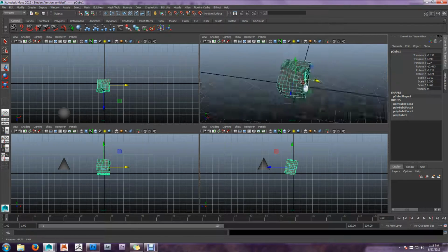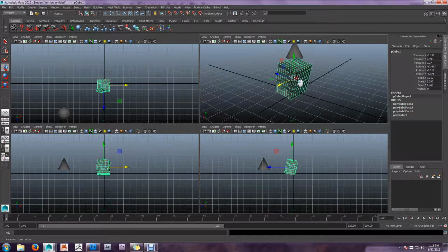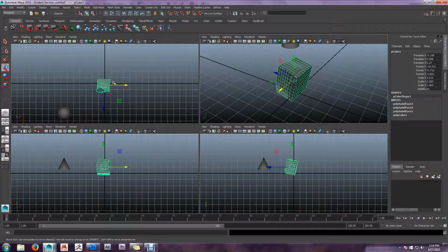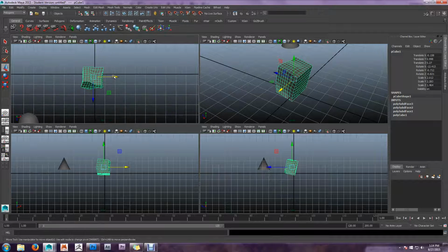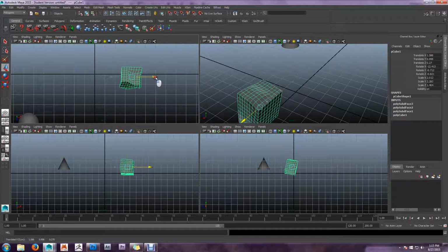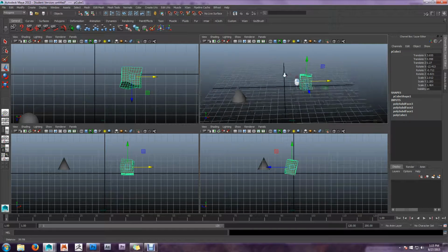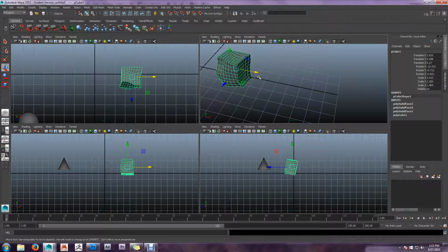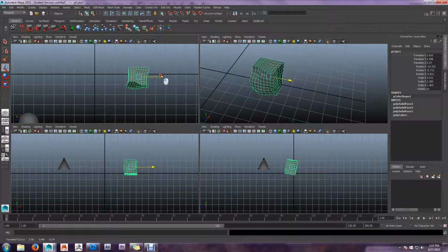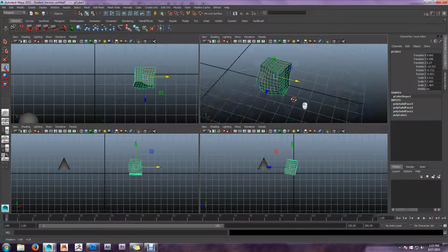You can sort of tumble around your objects in a scene up here on the top right hand side. And then if we want to see the object moving, say we want to make it move this way, in the positive X direction, and then we want to use the perspective view to view that happening. We can do that. We can move it in the positive X direction, while tumbling around here.